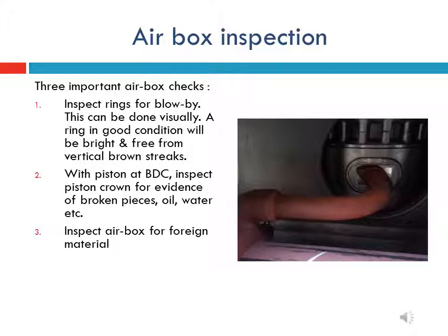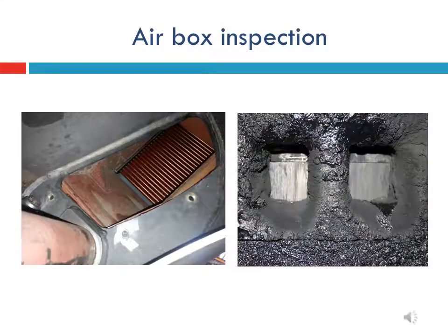Second, the crown of the piston should be clean. Carbon deposition should not be there. Third, the air box should be properly cleaned. In this slide, the condition of the air box of the engine has been shown. This is not good.